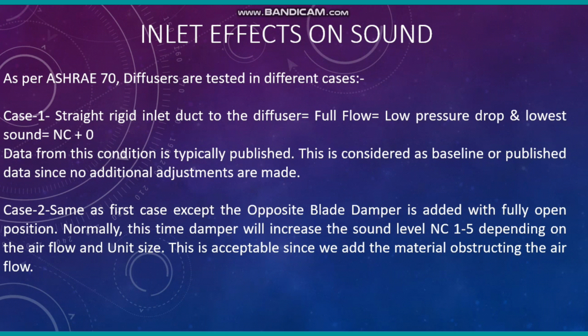So finally, the practical thing is what? The published data, technical data set, is based on the case 1 value. Okay, so when we come to the site, we are adding the dampers and we are adding the flexible duct, with the arrangement of flexible duct based on the site condition. So finally the NC value will be increased, like 8 to 10 NC will be increased.